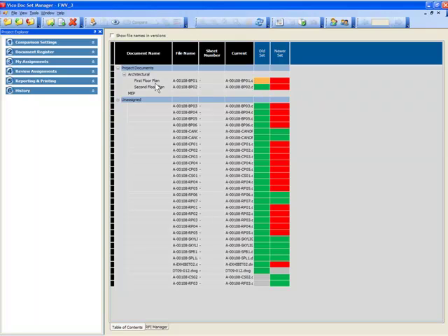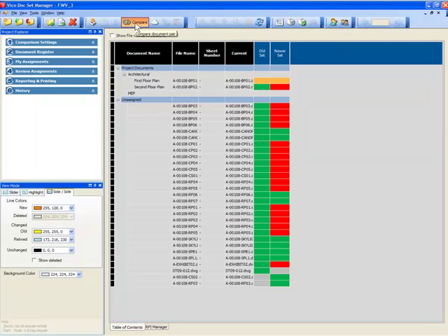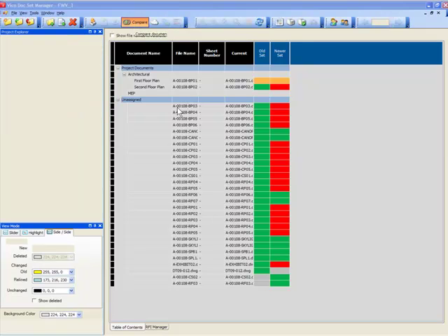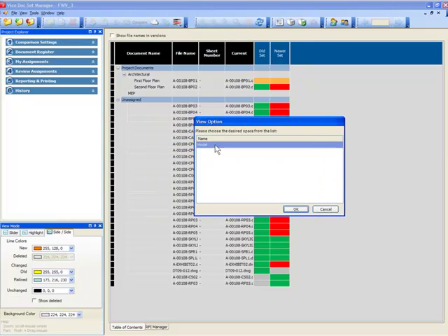So I'm going to select this drawing. Remember that it was green there. I'm going to click on that, and then click on its changed newer version. I just do that by holding down the Control key, and I'll hit this button up here that says Compare. And it's going to ask me, okay, what do you want to compare? Model space, paper space, or this is where the changes are being discovered in model space. Just accept that, and I will.